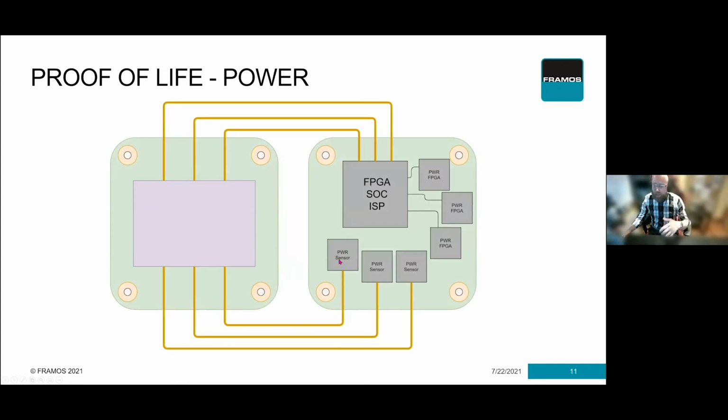So this would be the analog power rail, the power for the logic, the data comms, let's call it the communication power, as well as the interface power. These are the typical three. Please note that some sensors have up to 15 power supplies, with 6 or 7 different ones for analog and so on. So the complex and very large devices have that.